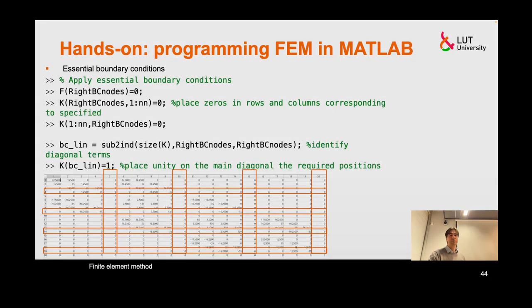So we cross out the 5th row of our global stiffness matrix, and the 5th column of our matrix. And we put zeros everywhere there instead of original values, and we put unity at the intersection of this column and this row. Oh, it's here. So sorry again, it's moved. I didn't notice that when I was adjusting to this format, and it moved this picture with respect to those rectangles.